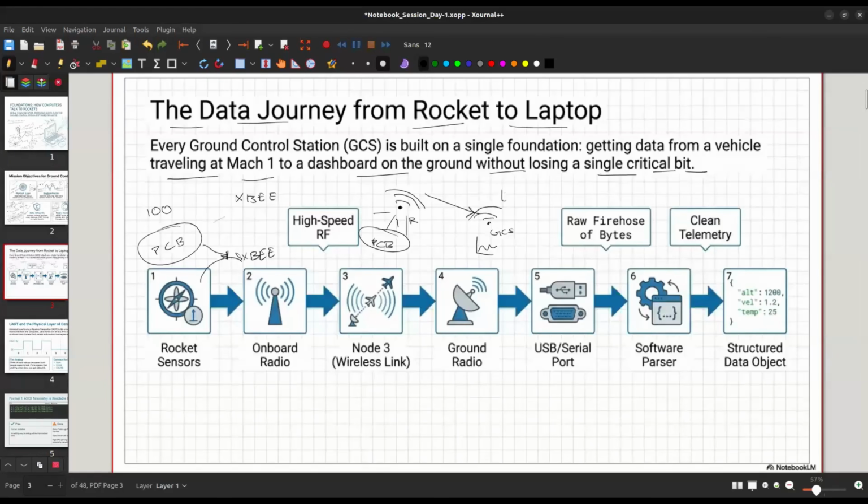How do computers onboard prioritize data from hundreds of sensors? They do not. If you're talking about something like ISRO, they have the capability to handle 100 sensors. Usually in our case, we don't need 100 sensors. What if a sensor fails and does not send temperature data? How will AI detect it by prediction? Well, let's say we have to set a few parameters for a sensor to work or not. You might run an AI model to predict whether your temperature sensor is working or not. But you have hard-coded systems such as the PCB. The only role of the PCB is to integrate all of the sensors together and send the data via Zigbee. So if a certain sensor is not working, you don't need AI. You just need a hard-coded system. It will automatically recognize that the temperature sensor is not working.